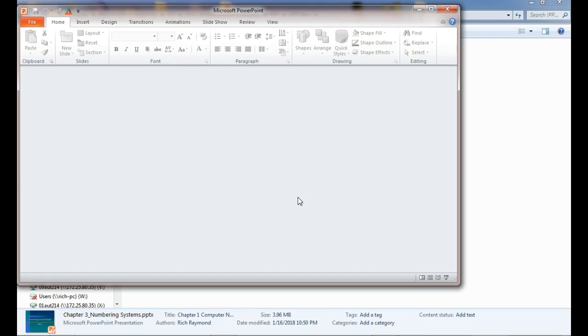So we've got instructions that do that for us. We have move instructions. We have move with mask. So I can actually take a number and I can mask it before I move it somewhere else, right? You understand? Strip off things. ORs. We have ORs. Logic ORs. So right now we know we can OR with contacts, but we can also OR. That would get very cumbersome if you had to OR 16 inputs. That means you'd have to put 16 inputs in parallel. Wouldn't it be nice if I could just bring that whole 16 bits into a register and then OR it with something with 16 other things?